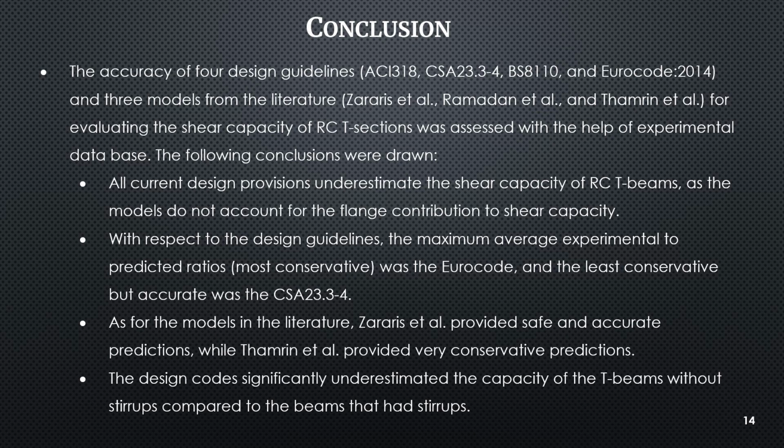As for the models in the literature, Zararis et al. provided safe and accurate predictions, while Tamrin et al. provided very conservative predictions. The design codes significantly tended to underestimate the capacity of the T-beams without stirrups compared to the beams that had stirrups.